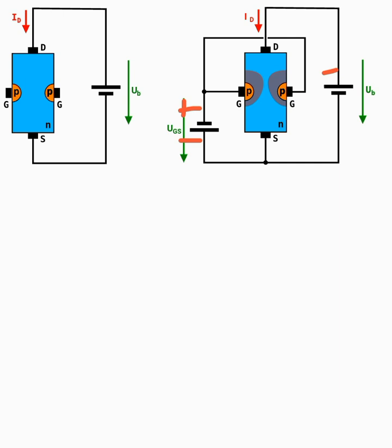Now let's see what happens if you apply a positive voltage to the gate with respect to source, and you have a positive voltage at drain with respect to source. With the positive applied to the gate, the P-type semiconductor on either side of the N channel bar receives the positive voltage, and the N is connected to the negative potential.